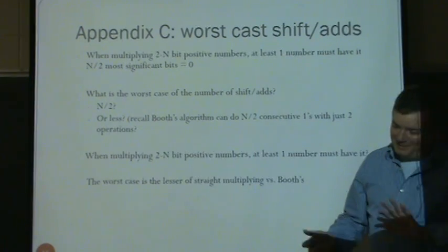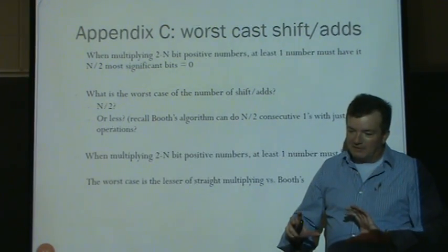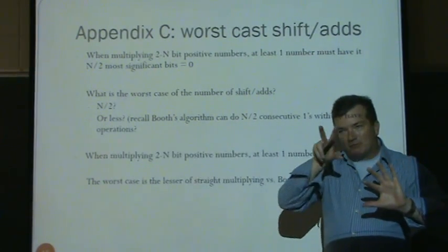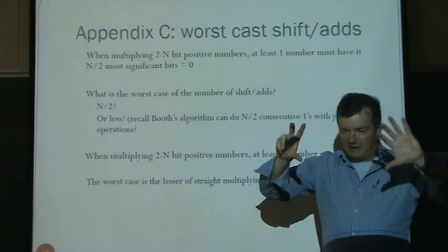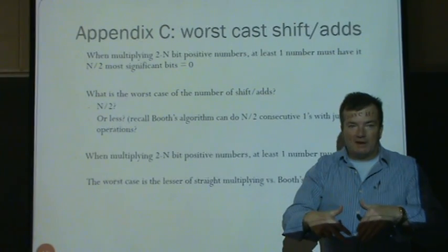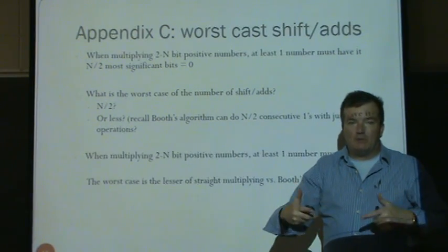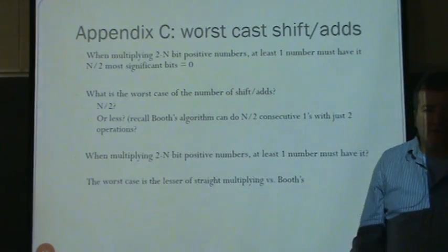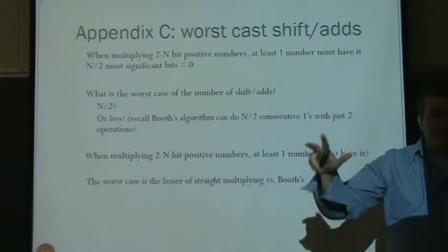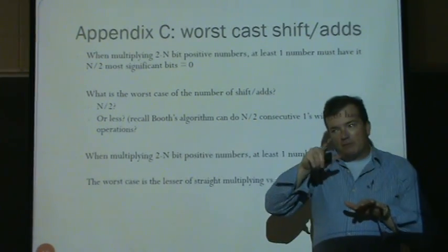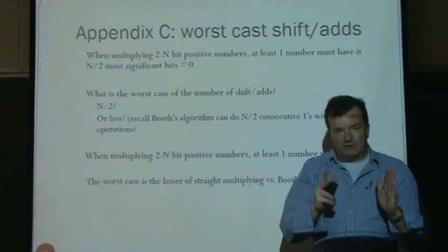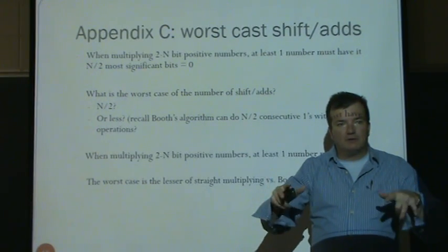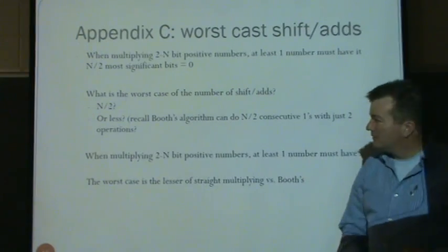The way they designed a lot of processors in the 80s was to use Booth's algorithm and not Booth's algorithm, and have something read the number to say which of the two would be faster, and always have the two results come out and feed them into one answer. And whichever one is faster, take that answer. And you'd have to only allow enough time for whichever is the quicker of the two, because both will compute the correct answer. Based on the number of ones in the lower half of the number, it would determine which one could calculate it faster. And then you only have to allow the clock enough time to get either answer to come out, because we'll have the correct answer. Okay.